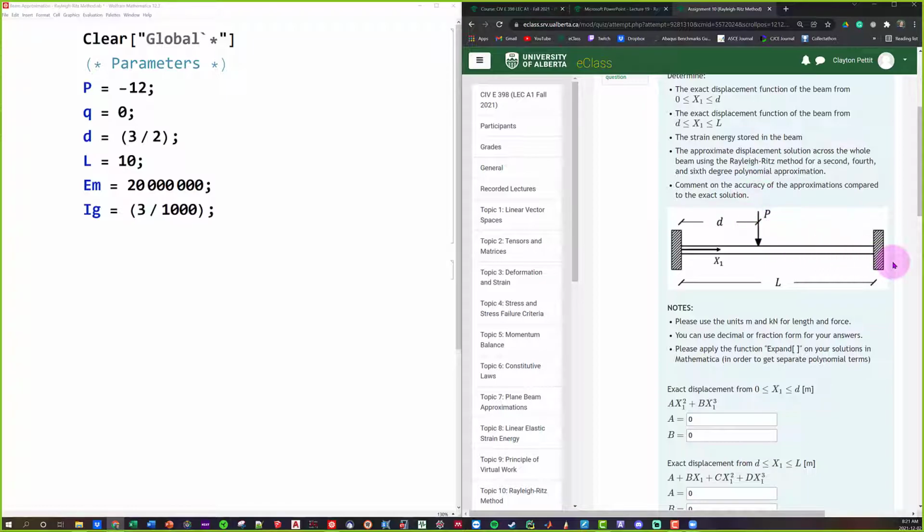Now, one common misconception is this: I would have to use the DSolve function twice. When we're solving two differential equations, we actually only use the DSolve function once, because as we can see, at point D right here, we're going to have a lot of boundary conditions that relate the left-hand displacement to the right-hand displacement. So since our two displacements are two separate functions, but actually they're intertwined with each other, we have to use the DSolve function basically just once.